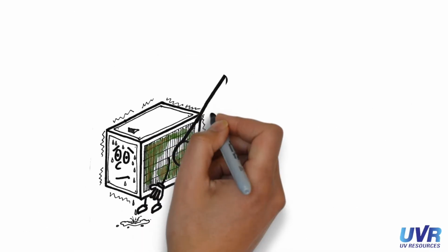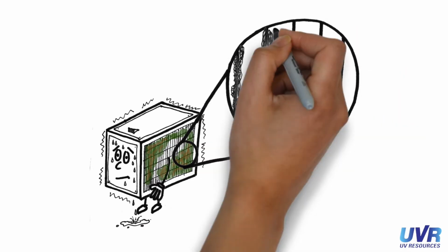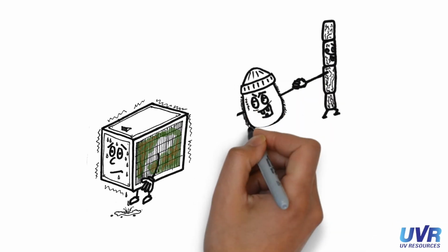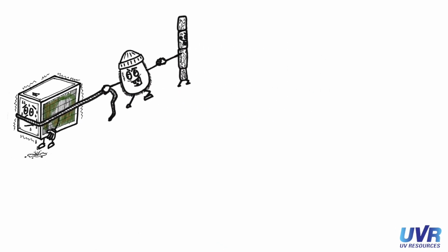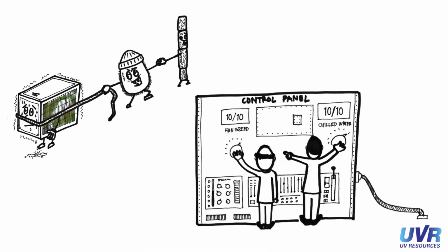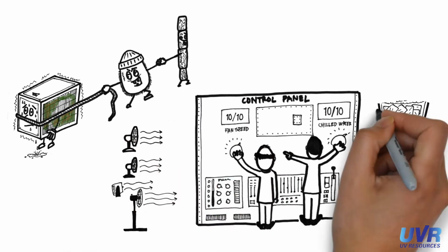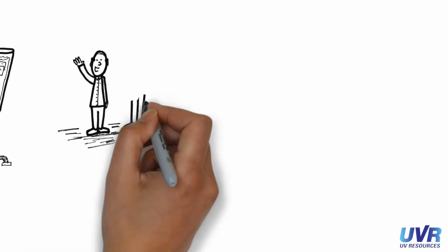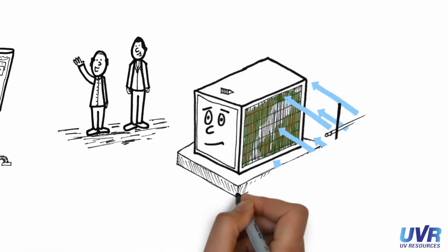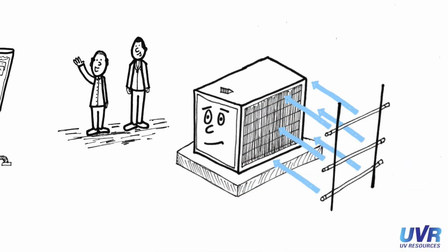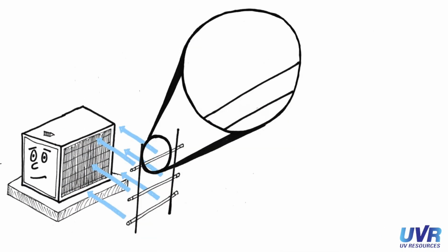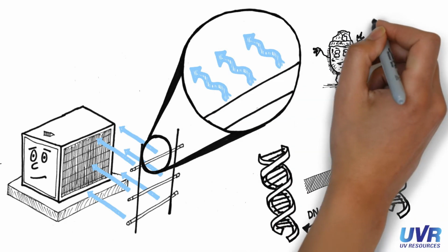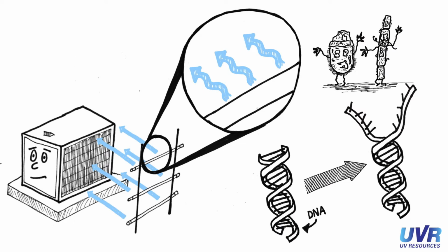Think of mold, biofilm, and other organic compounds like a layer of insulation. The thicker that insulation, the harder your system must work. To meet demand, operators often attempt to compensate by speeding up fans, pumping more chilled water, or lowering system water temps. But many HVAC insiders have turned to germicidal lamps to remove microbes from fouled coils and guard against their return. UVC energy disrupts the microbe's DNA, so this zombie apocalypse is never going to rise from the grave.